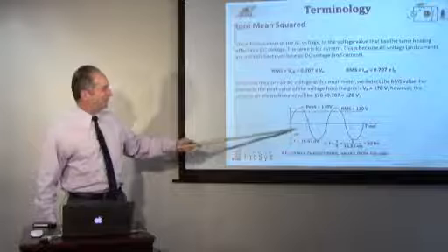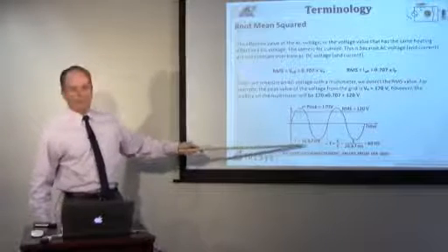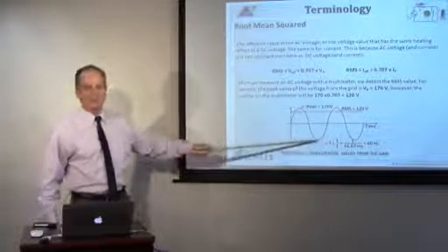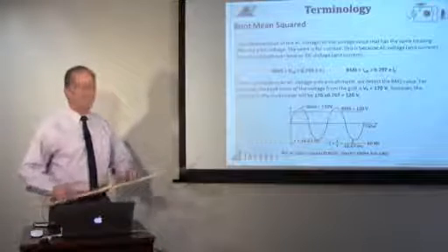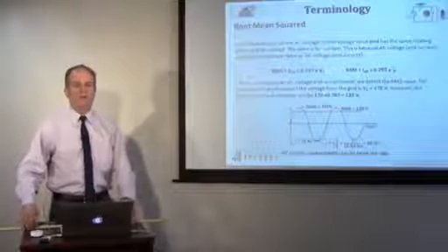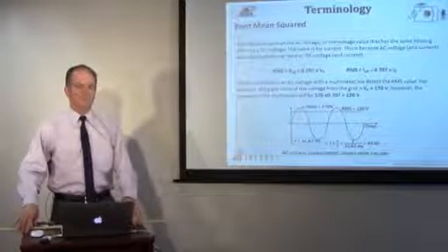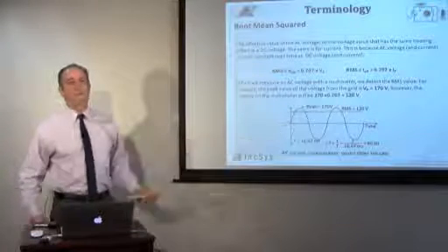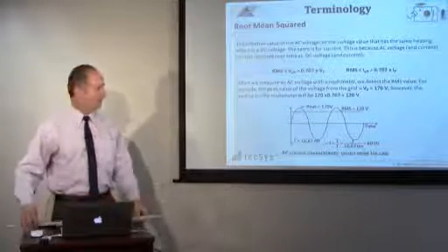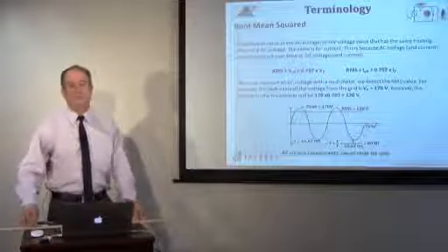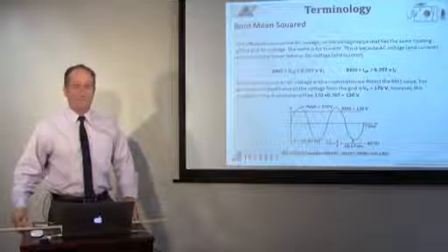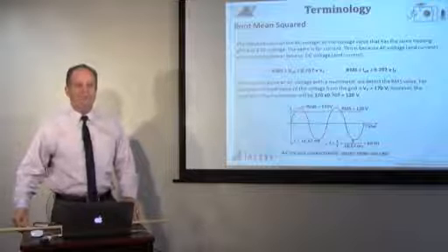So that's the time it takes for 1 cycle, 16.67 milliseconds. And that's pretty short. But what's really interesting is some of these very large circuit breakers used in bulk power systems can open up the circuit in roughly 2 to 3 cycles. So 30 to 40 milliseconds, we can de-energize a complete high voltage transmission line.